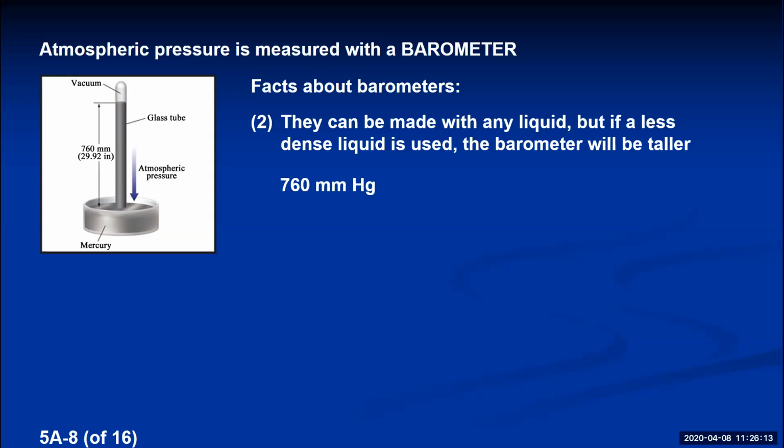So if we have a mercury column that's 760 millimeters high, I know that the pressure of 1 millimeter of mercury would be equivalent to 13.6 millimeters of water. If you're supporting 1 millimeter height of mercury, because water is so much less dense than mercury, you can actually hold up a column of water that's 13.6 millimeters high.